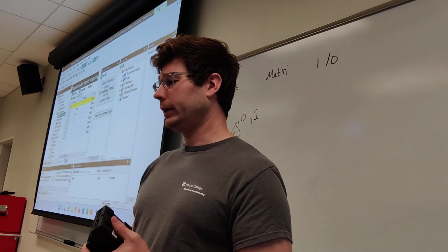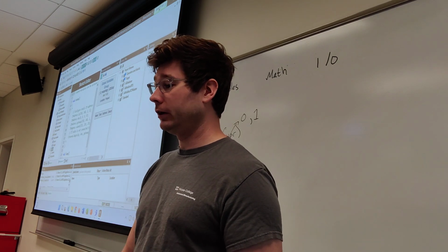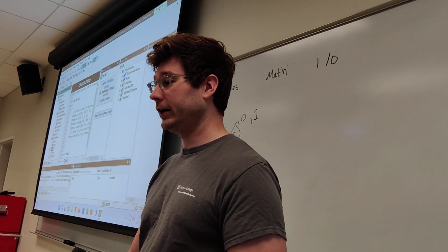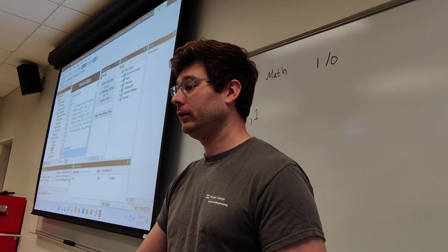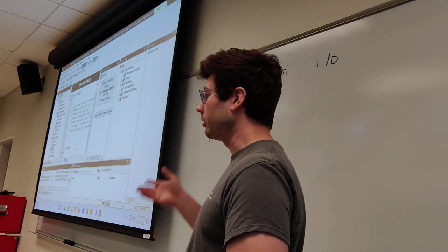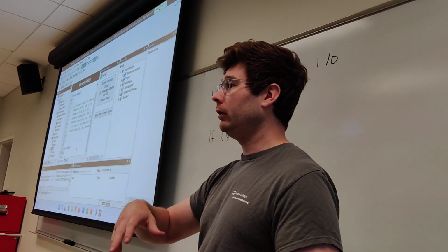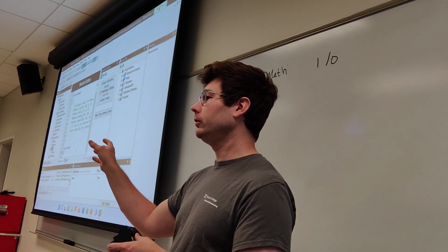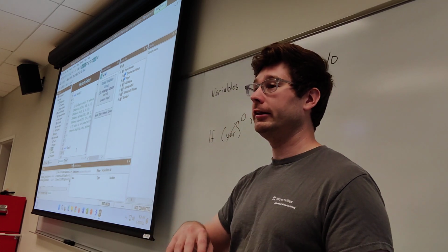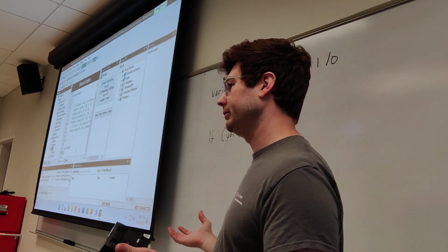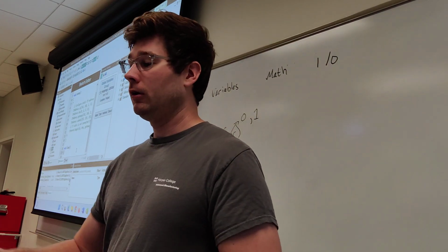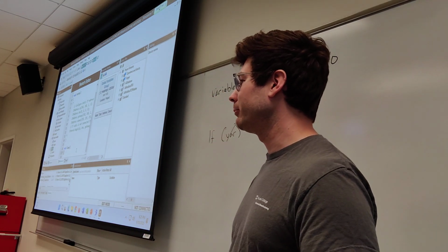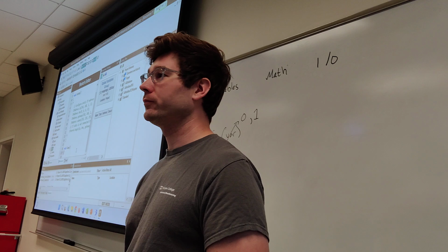The only other thing that I would like you to know is that this is where the Arduino stuff lives. If you know Arduino or are interested in looking into it, by double-clicking Sketch, this is how you access the Arduino programming bit. If you write Arduino code in here, when you compile and upload code to the device, this will go to the Arduino coprocessor, and then the PLC code will go to the PLC processor. Then they can share variables and crunch data and do cool stuff like that. But we'll get into that later in the class. You will be plenty comfortable with the program by the time we get into any of that, so no worries.